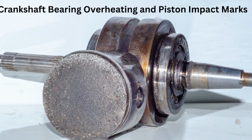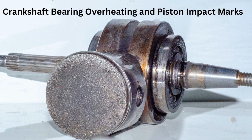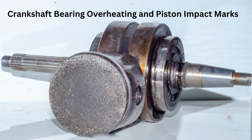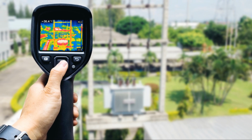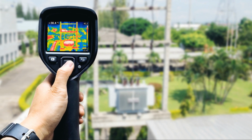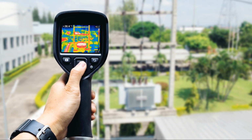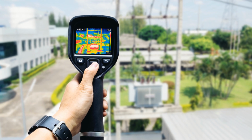It pinpoints incipient bearing wear, inadequate lubrication, or mechanical rubbing, which may not yet show as significant heat buildup, but will eventually lead to overheating and failure. By integrating ultrasound testing with thermal imaging and vibration analysis, maintenance teams gain a comprehensive view of equipment health, enabling early intervention and targeted maintenance actions before minor issues become critical failures.